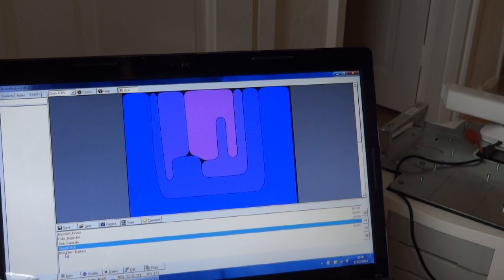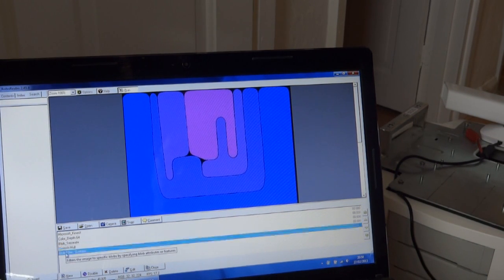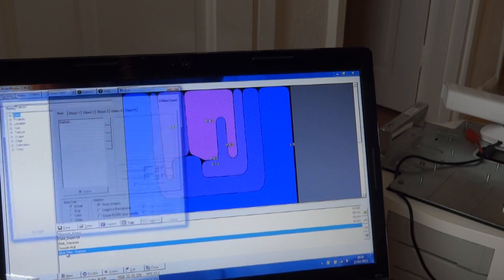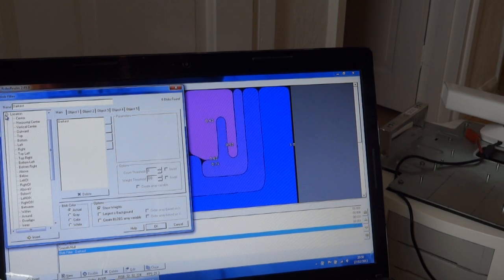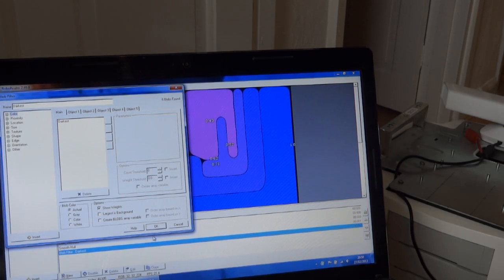And then I've used blob filter to track the blobs. This is quite a good function where you can match by colour, darkest, brightest, a specific colour match, proximity to the top or bottom of the image, as well as location, the size of them if they're over a certain pixel size, and basically we can assign a weight to every blob by ticking this box. And all of this data is presented through the API.